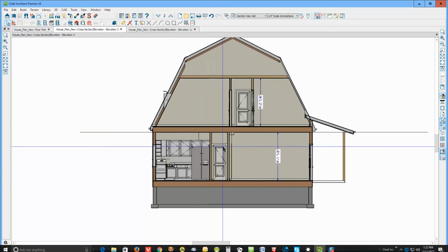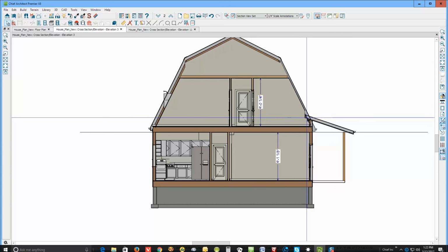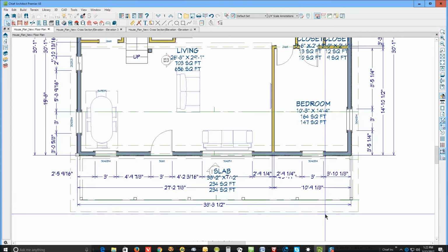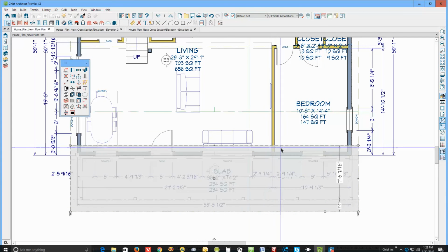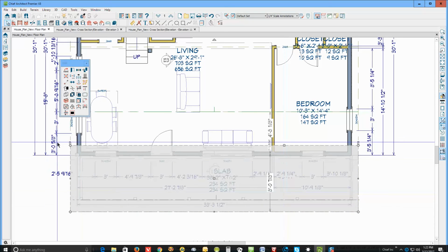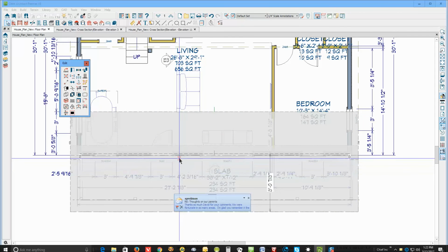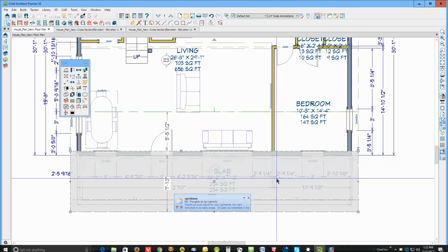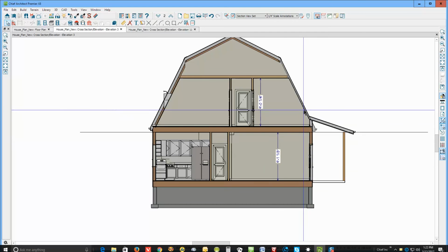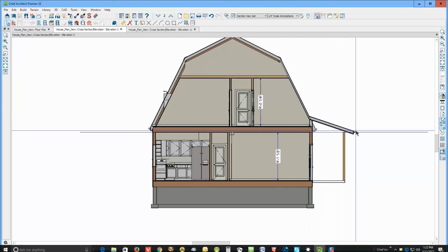Okay, this is beginning to, that's sticking in a little bit too far into that roof plane there. So what I want to do is click on this edge of this roof plane and tie it into this roof plane using the join roofs tool. We'll get a hopefully clean connection, yeah, that's a little bit cleaner where the shed roof comes in.